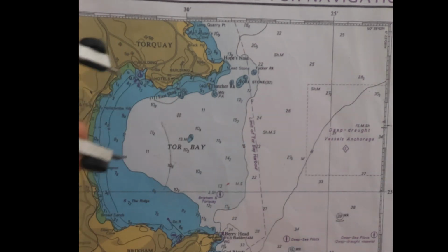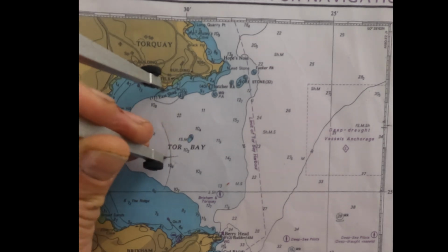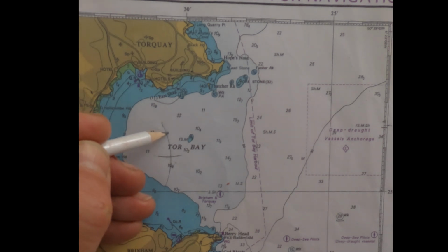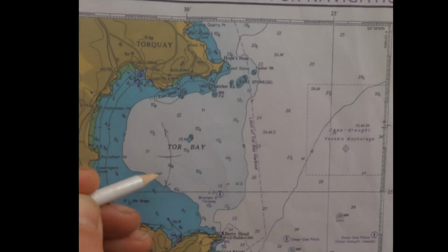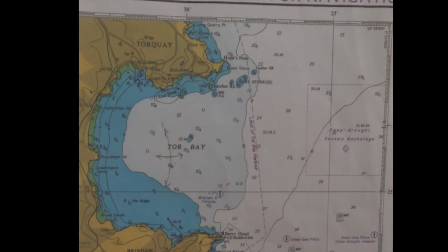So we take that from the rocks on East Shag, mark it off. Okay, where they cross over, so bear in mind at the moment it's only a 2-point fix. Where they cross over, at the end of the lines, we put an arrow, as we would with any position line, and we're going to have a look at the bearing from Roundham Head.